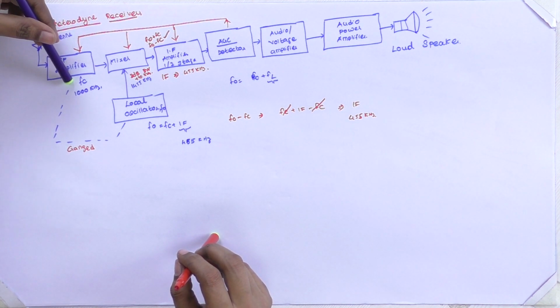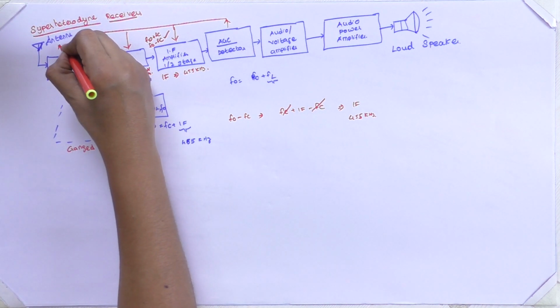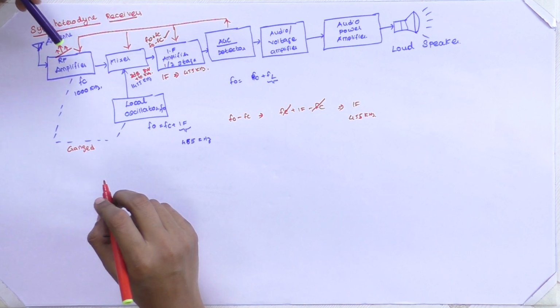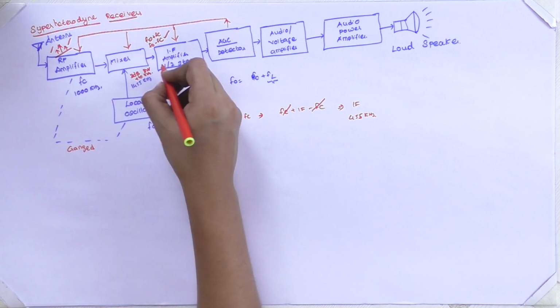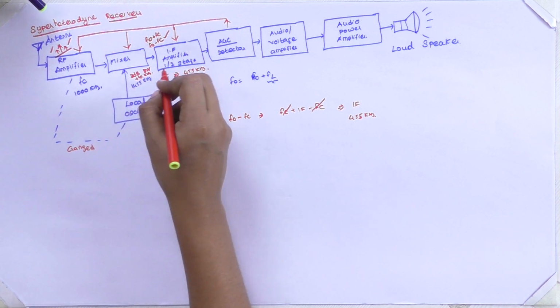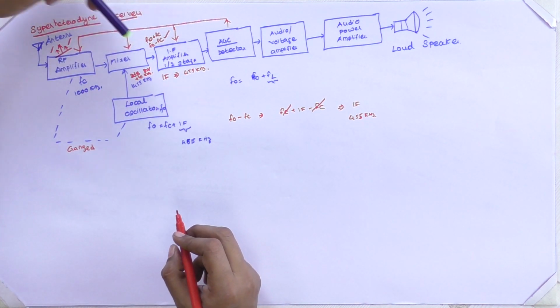In conventional AM, we will have the carrier signal as well as the lower sideband and upper sideband. In the case of DSB-SC, we will have the upper sideband and lower sideband alone. Therefore, our stage should have a sufficient 3 dB bandwidth to accommodate plus or minus 10 kilohertz, so that all the sidebands will pass through the circuit.